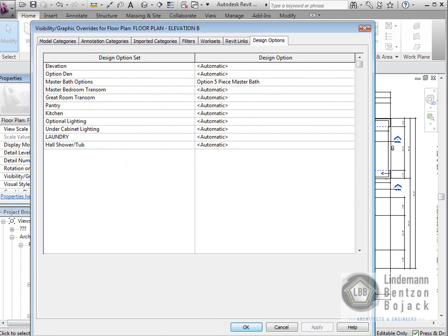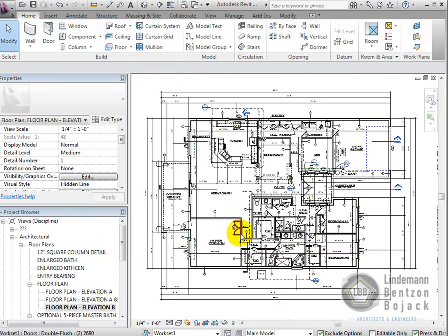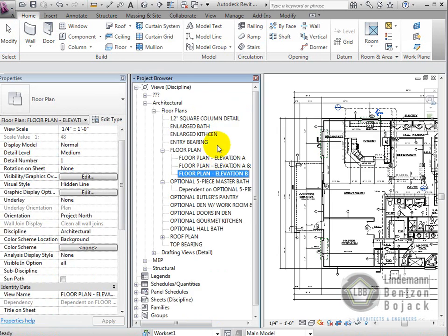We're going to go over several lessons on work sets and design options, which will make a lot more sense. But within these visibility settings, a lot of times, especially when I create foundation plans and you have unique cut planes and items like that, you can never get anything to look correctly. But in one particular view, it looks right. And you want to be able to apply those settings from that view to another view. And that's where view templates are a good utility.